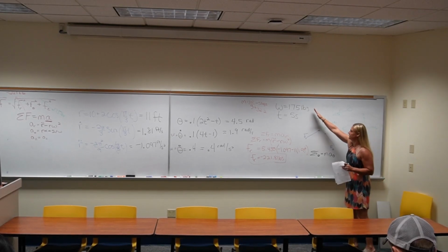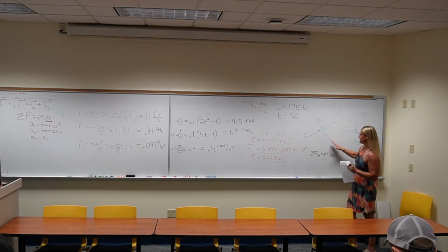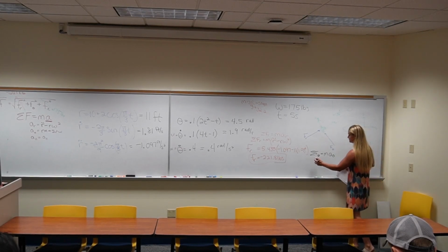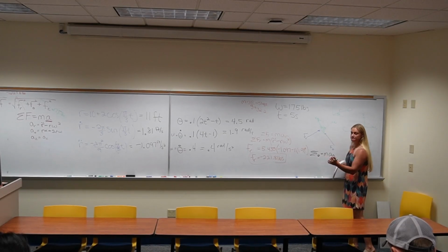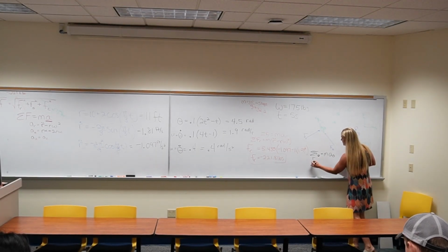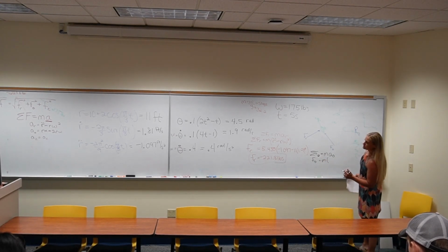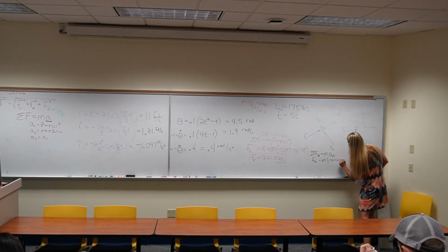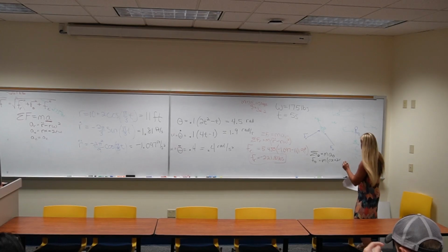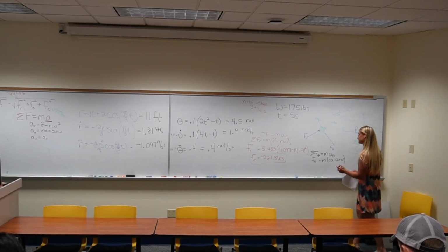What are the sum of the forces that occur in this direction? F in the transverse equals M. What was A in the transverse? R alpha plus 2 R dot omega. R alpha plus 2 R dot omega, thank you. Okay.